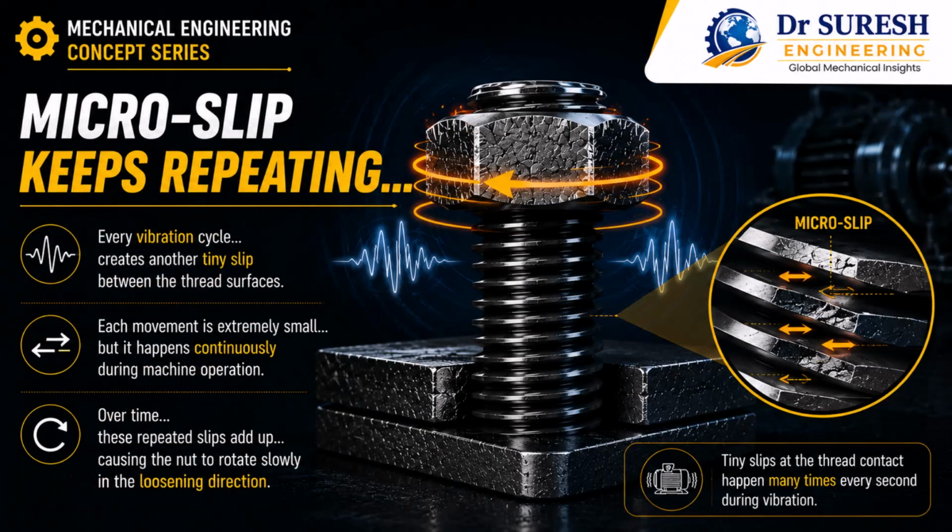Microslip does not happen only once. It repeats continuously every time the machine vibrates. Each tiny slip at the thread contact surfaces creates a small relative movement. Individually, these movements are extremely small, but as vibration continues, the slips keep repeating again and again. And slowly, these repeated micro-movements cause the nut to rotate in the loosening direction.